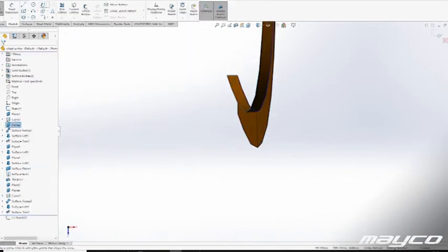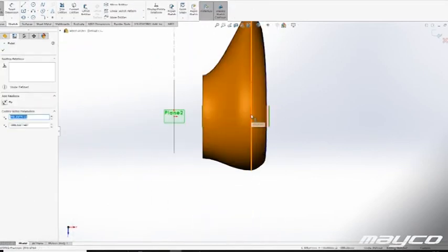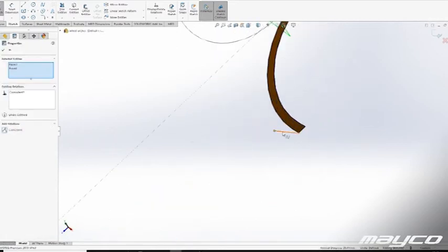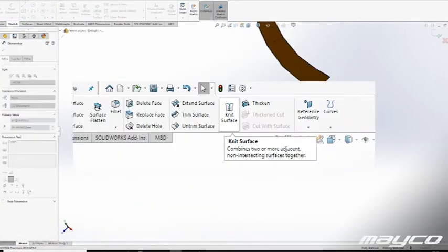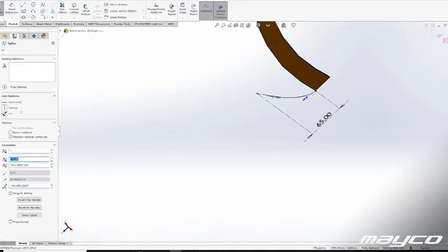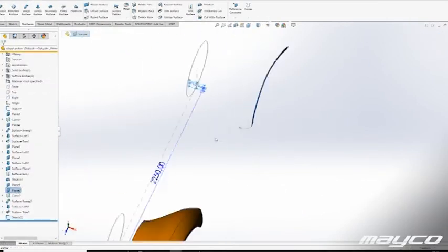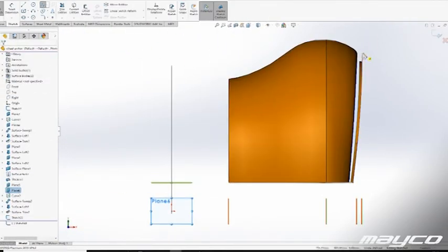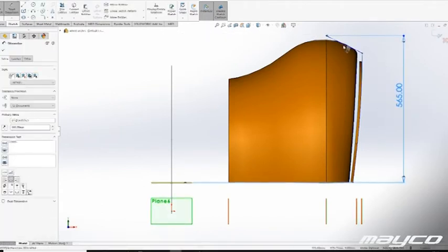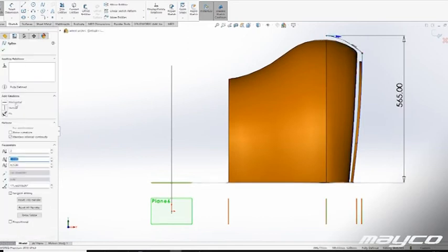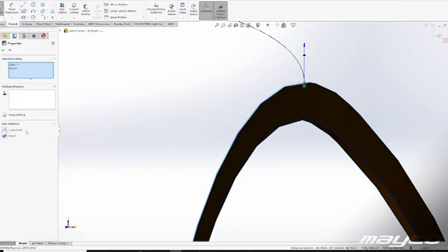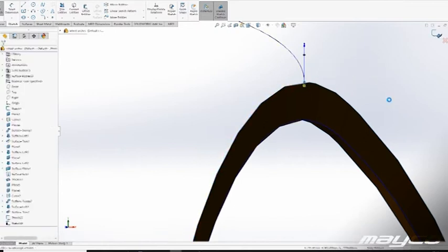Another thing that you often see if you try to go to solid bodies: if you select one or two and then knit them together and make them into a thick part, a body, it'll work. But if you select everything, somewhere something goes wrong. And it's very frustrating, it's very difficult, and it's not an exact science. There are some things to look out for, as I just mentioned, but in general it's just trial and error, and try to work as nice as possible.